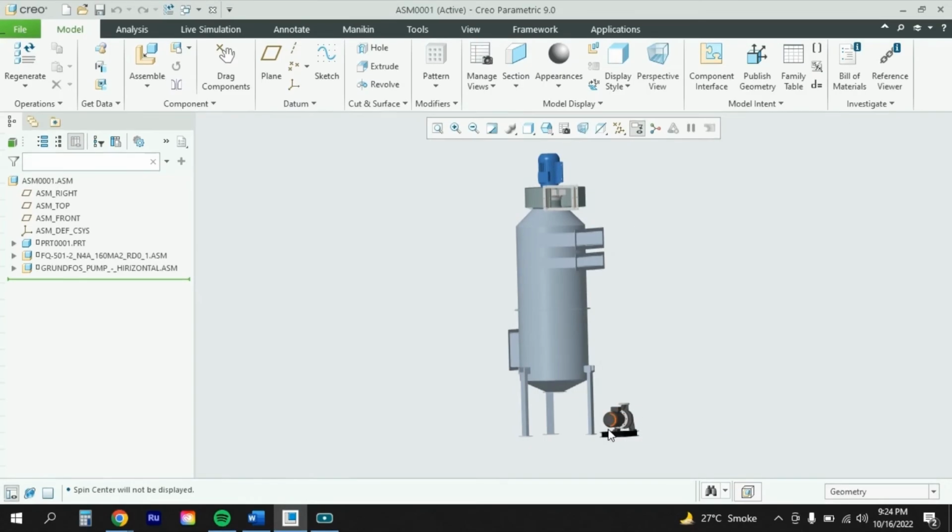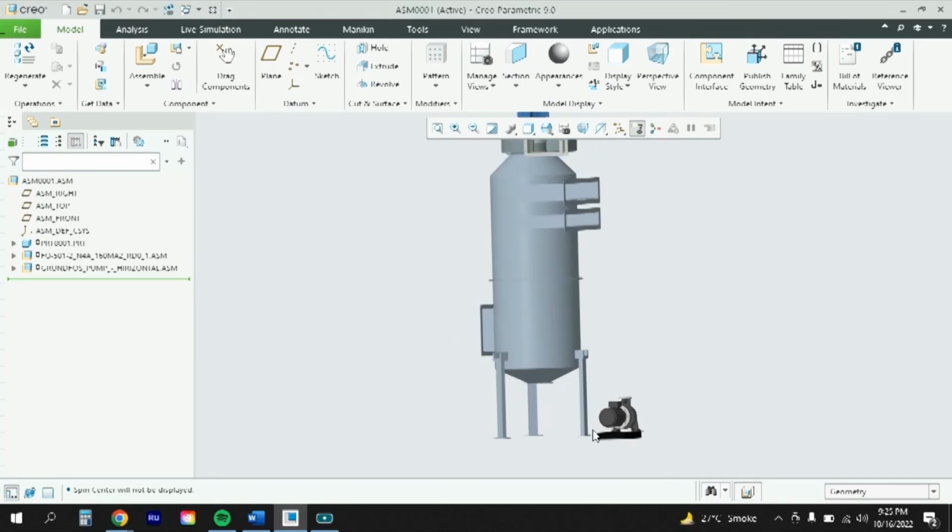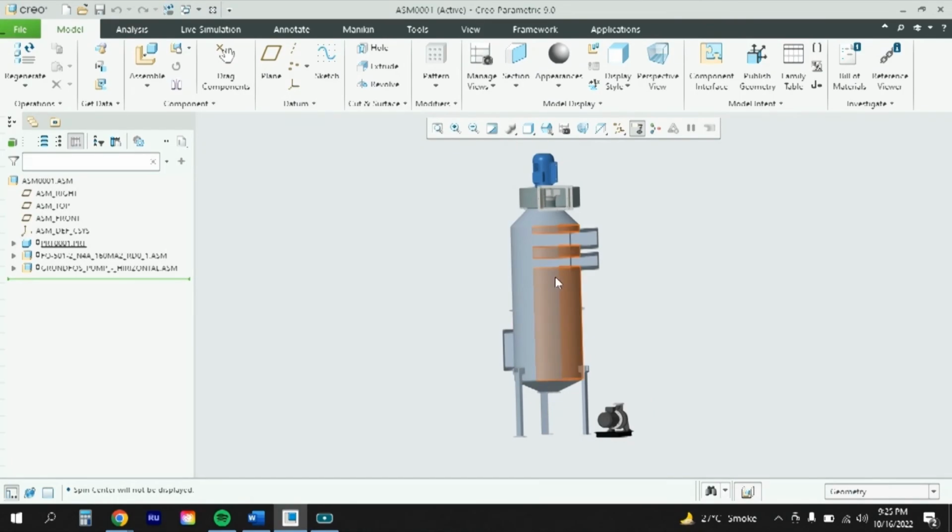There is another thing which you can do for recirculation. You can prepare a tub of steel below, and you can make a partition there. So once the dirty water is coming and falling down, it will be collected here in one side of the tank, and the heavier particles will be settling down. So the fresh water will be coming into the other chamber, which would be more or less clean water. Then for this pump connection, you don't need to give a fresh water connection.